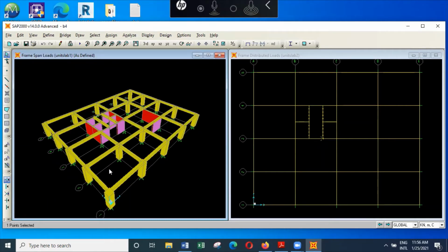The problem is, when you try to do that in a large building having 30-40 floors, each slab will have so many shell elements. And when you consider one particular level, there will be a lot of shell elements. When you consider about 30 to 40 floors, there will be an enormous number of elements, and because of that, the program can become fairly slow when it comes to running.